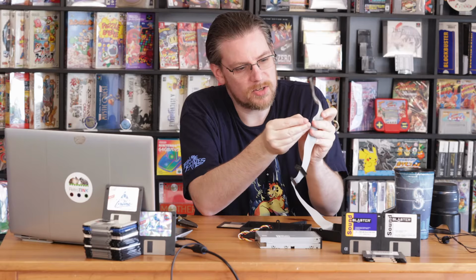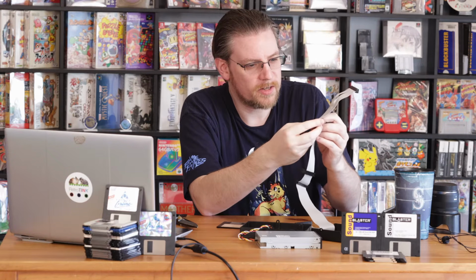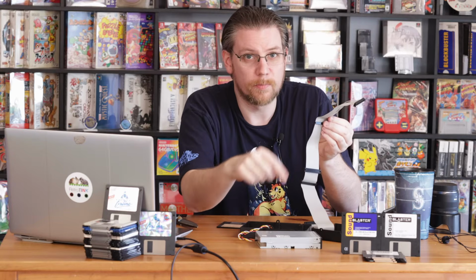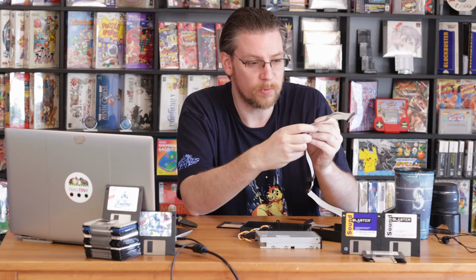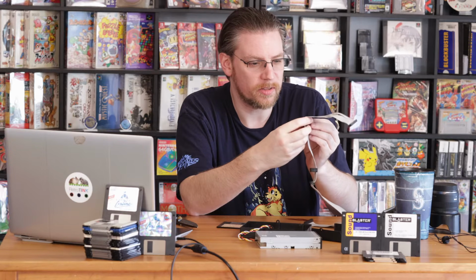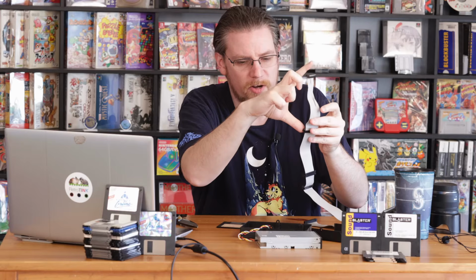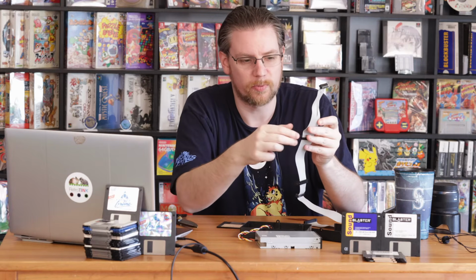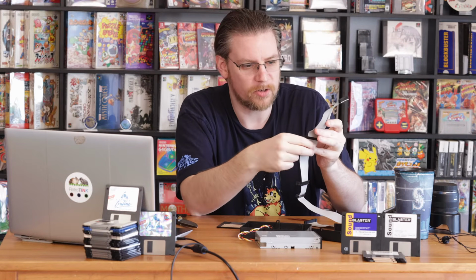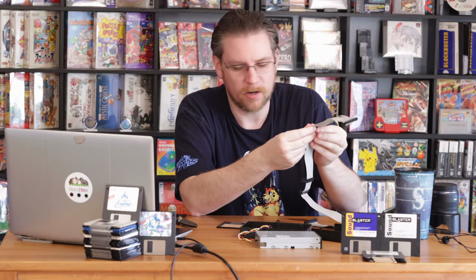All right, so let's get this in here, slide that back in, and validate exactly how this looks, because I'm looking at the board here to see where pin 1 is, which is this red stripe, matching to where the key is for this clip. So let's get this lined up. That's probably about a good amount of length, considering it's just going to loop really shortly there, and I just need to have that twist in there. So let's get this pushed up just a little more. I'm going to have it right about there.